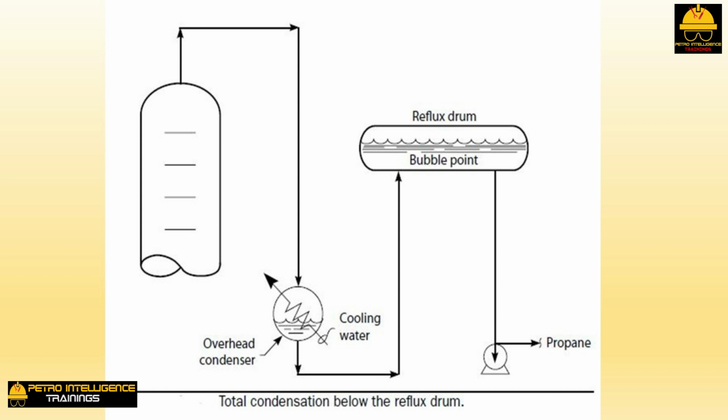I have another way to explain how the condensed liquid can flow uphill from the condenser into the elevated reflux drum. That is, the liquid leaving the condenser is pushed into the reflux drum by the higher pressure in the tower. This will work okay, as long as the liquid entering the reflux drum is at its saturated bubble point temperature and pressure. If this is not the case, then the vapors flashing out in the reflux drum will have to be vented. If you refuse to open this vent, then condensate backup must increase in the condenser, with a consequent reduction in the condenser's capacity.